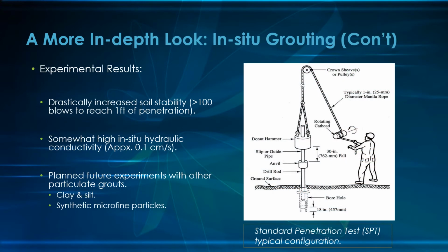So after the experiment was conducted, some of the results are highlighted here. It definitely increased the soil stability through a standard penetration test. It required greater than 100 blows to reach 1 foot of penetration. So it's very stable. It should be since it's concrete. And it still had somewhat of a high hydraulic conductivity going past it. And so in the future, they plan to expand with different kinds of particulate grouts, such as finer ones like clays and silts and synthetic microfine particles, to possibly diminish that hydraulic conductivity.